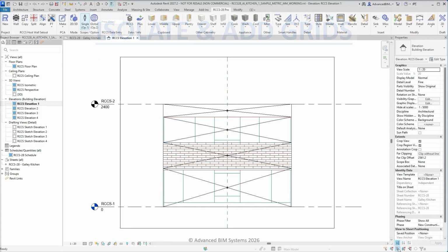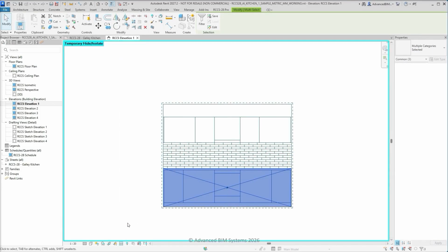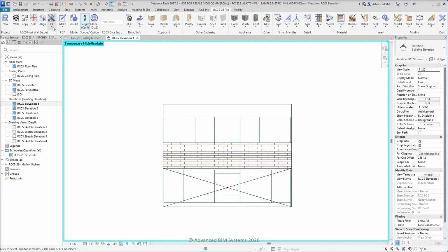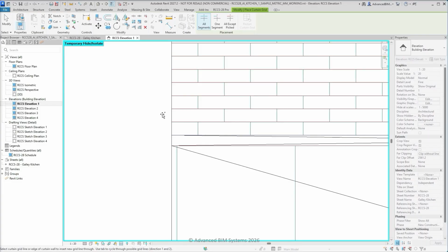The easiest way to add grids is to first isolate the reference sketch as well as any of the host wall segments, and then add the longest edge-to-edge grids first, followed by any grid segments, working from the outer grids to the innermost grids that trim in between.